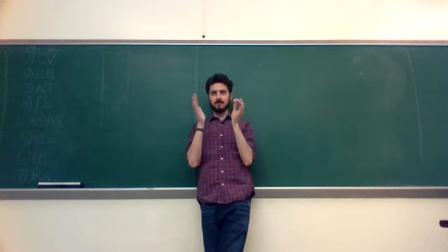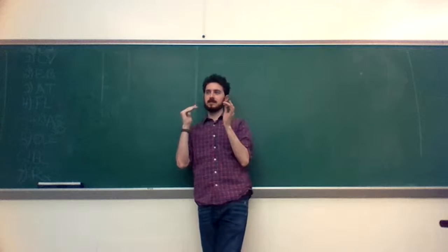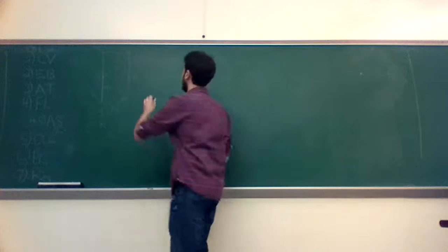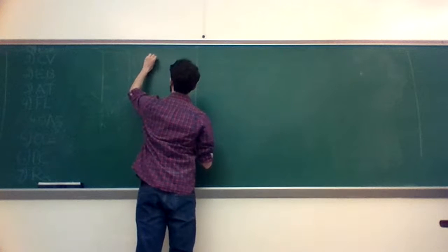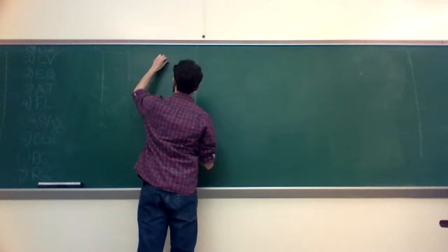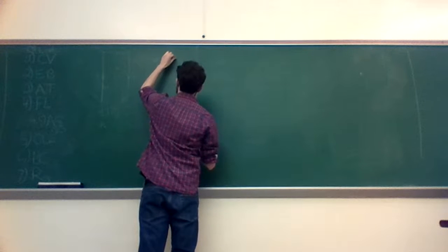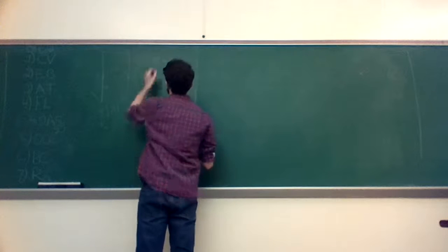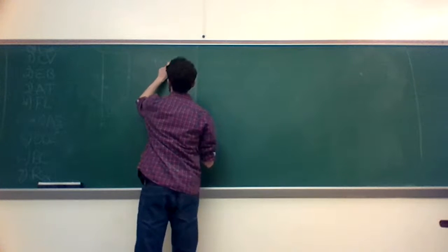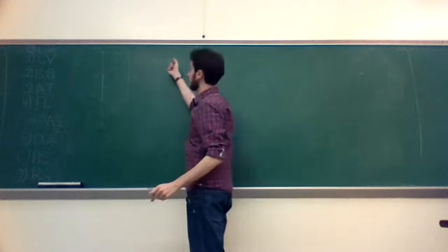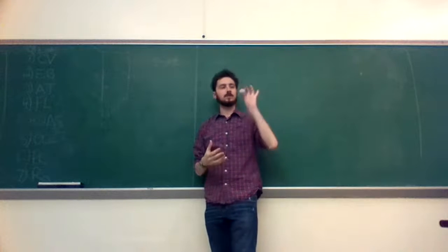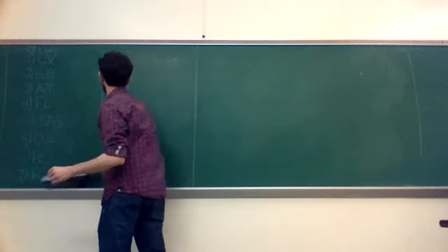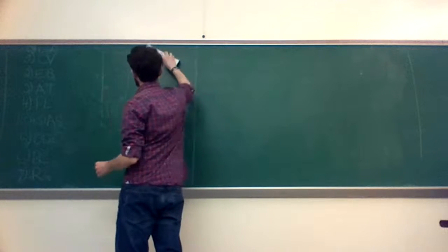So if there's no heat flux at the middle, what does Fourier's law tell us the shape of the temperature distribution is going to be? Yeah, so q double dash, the flux, is negative k dT/dx, right? So if q is 0 and k is not 0, then it's dT/dx that has to be 0. So it's going to be flat. Okay, I would say we have sufficiently communed with the problem.